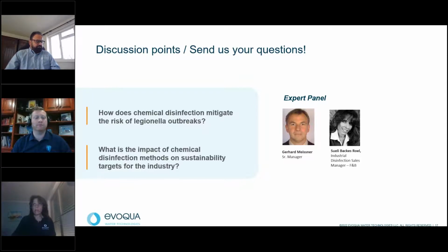Please allow me to reply to the question, how does chemical disinfection mitigate the risk of Legionella outbreaks? It needs to be known that Legionella are contained in fresh water almost everywhere, and they spread quickly in the plant pipework, with a doubling time at 45 degrees Celsius of just 3 hours. This especially applies for dead water ends, where they spread and live in the biofilms. Legionella do not survive temperatures above 55 degrees Celsius.